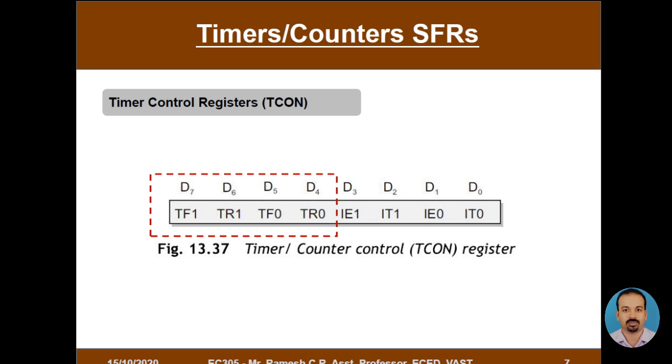So this transition of the timer counter register from FFFFH to 0000H, that is from the maximum value to the initialized value on the occurrence of a clock pulse, is considered the overflow situation. Once we start the timer and this overflow occurs, it is indicated by setting the value of these bits TF1 and TF0.